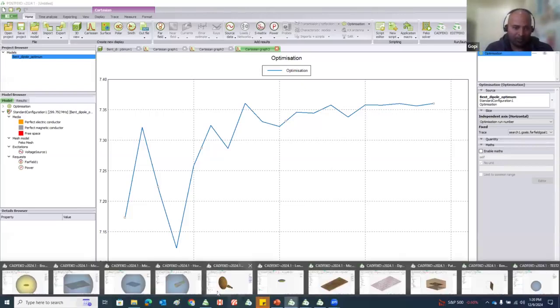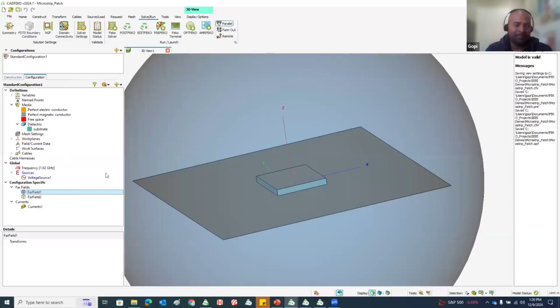Okay, so when you use Feko, as I said, if there is a frequency range, by default, Feko takes into account the material properties as well as the highest frequency and comes up with a mesh. Okay? So I would say more than 90% of the time that should be good enough. But if you still want to do a study to test if the default mesh you have is the right one or not, there is something called adaptive mesh refinement in Feko.